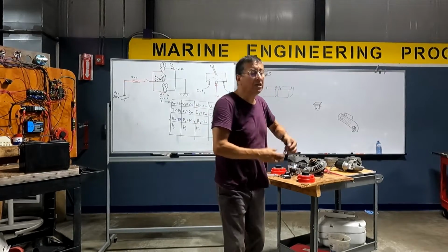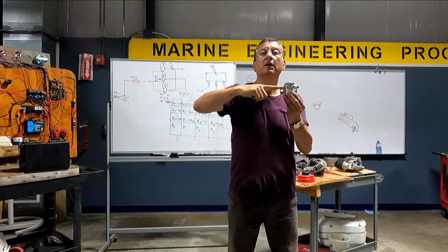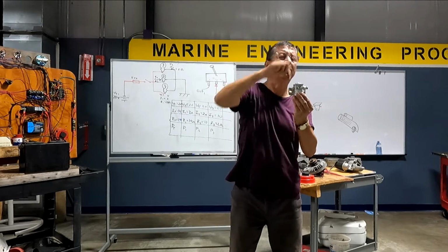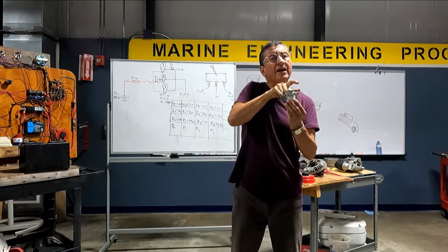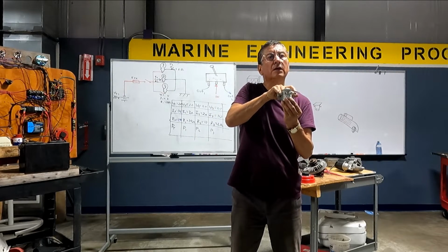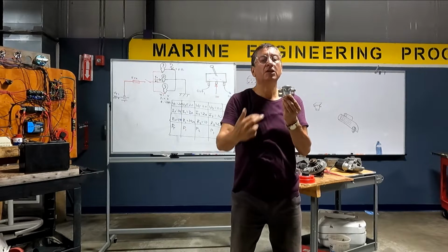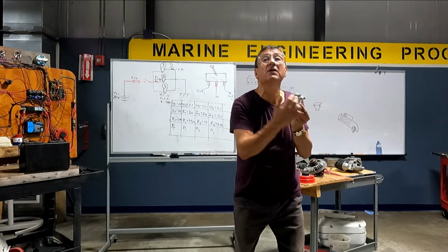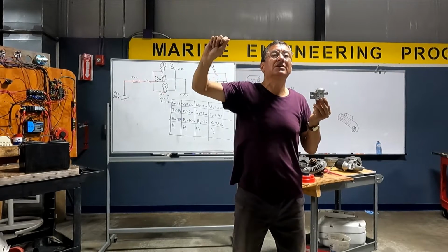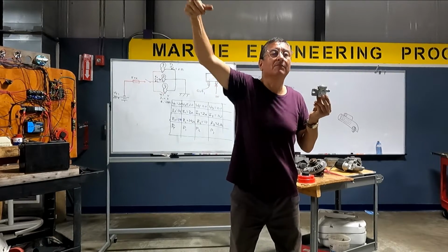Okay. What about this? I have the current entering here, and this is the output, or vice versa, doesn't matter. This is the input, and this is the output. But at this moment, do I have continuity here? Is this connected with this? No. Until you bring a signal, a small signal, positive and negative, from the ignition switch, from the flybridge, from the pilot's hand.